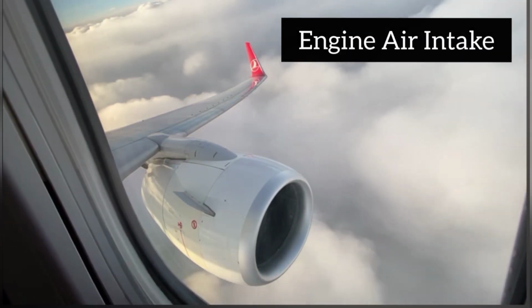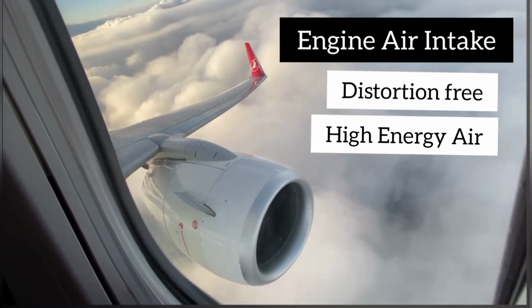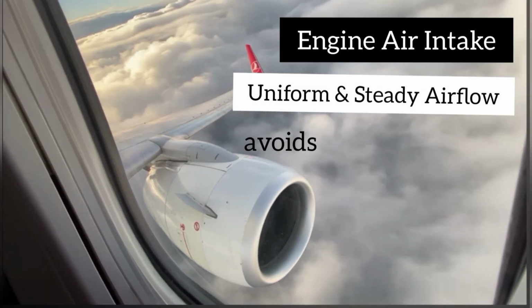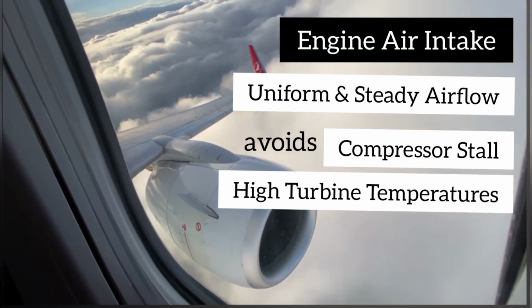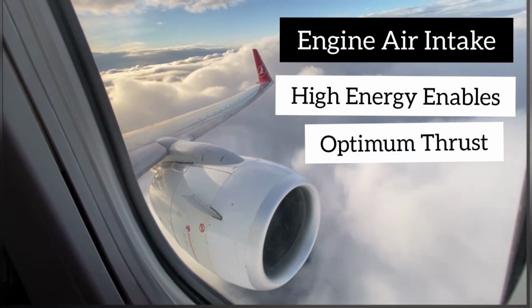The engine air intake provides a relatively distortion-free, high-energy supply of air in the required quantity to the face of the compressor. A uniform and steady airflow is necessary to avoid compressor stall and excessive internal engine temperature at the turbine. The high energy enables the engine to produce an optimum amount of thrust.